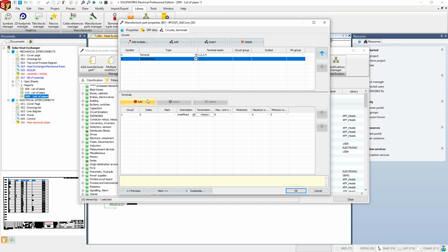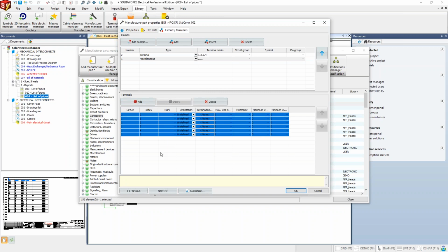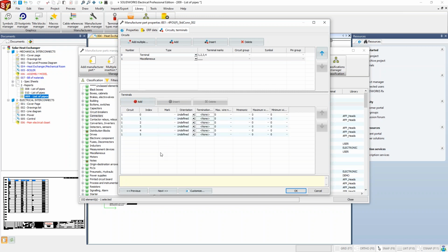So in the case of that pump, I would have one be for the cable and the wires coming out, and maybe two because there's an in and out for the piping information on there. So I can have several different terminal circuits within that, and I can have multiple instances of that circuit, terminals within that circuit. Hopefully that makes sense. So yes, the answer is yes, you can within a symbol define multiple, including the electrical and mechanical aspects of that component, whatever it may be.